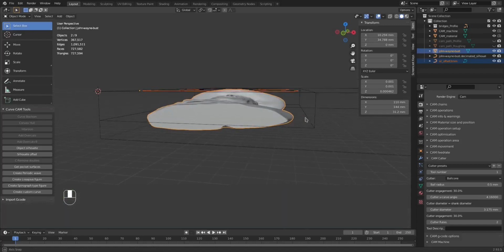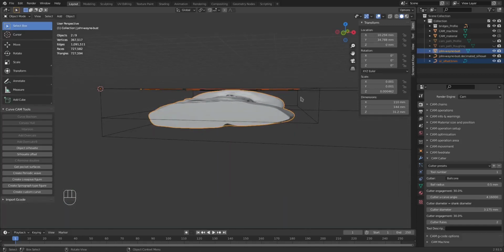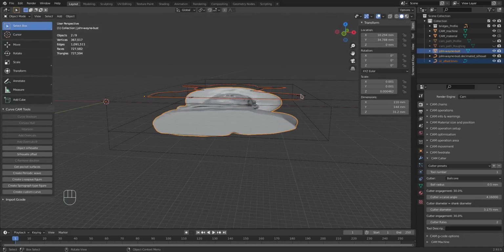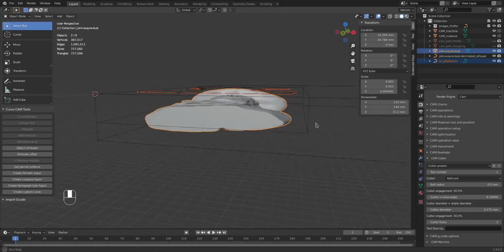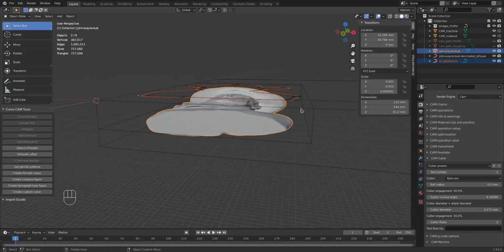I'm actually doing something somewhat unsafe. You shouldn't do this. You should probably go with a better bit, a longer bit, or a thinner piece of material. I'm having to extend my bit a little bit further out of the collet. I hear that can be a safety issue. So if you're wondering, that's why those numbers are off. But I don't recommend doing that. I'm actually going to have to find a longer bit in the future. Yeah, I think we're good to go.